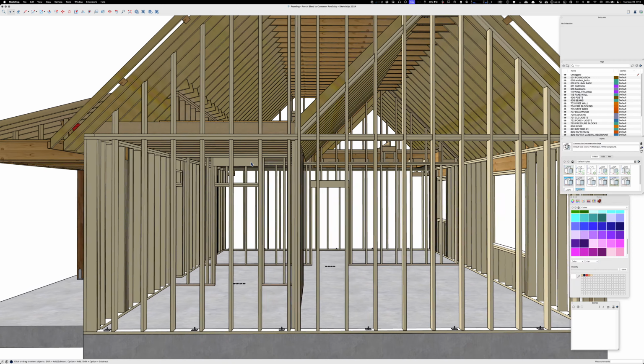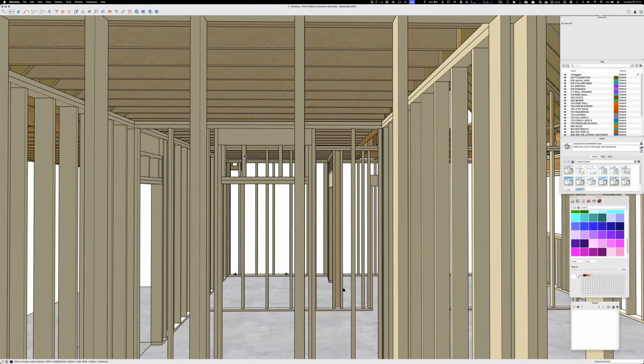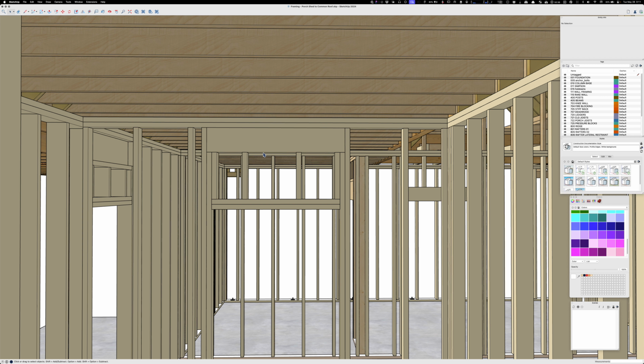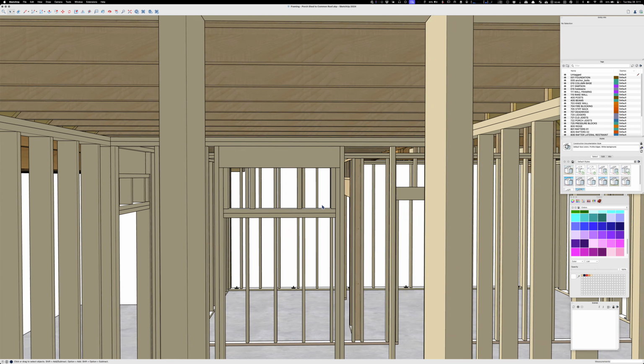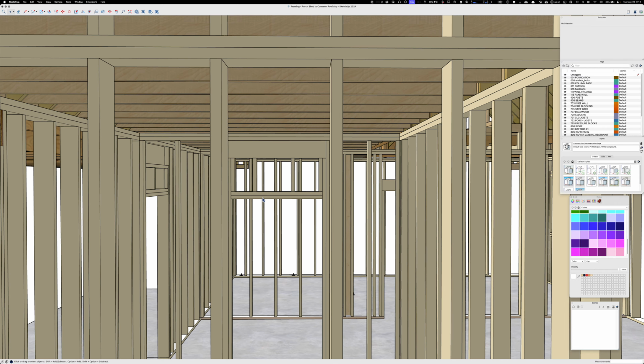And I like to do headers to the top, and the only reason is because we did a hotel in Clarksville, and no, it was assisted living, and on the ground floor they sent doors that were 2 inches taller than what the plans called for. There was some kind of metal fire rated door, and we had all the headers down like they're supposed to be normally.